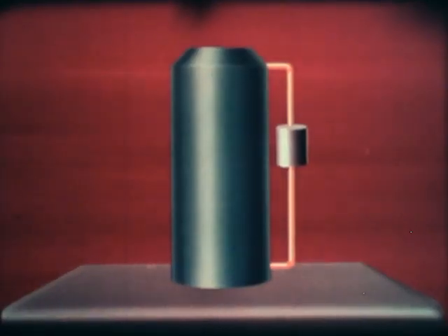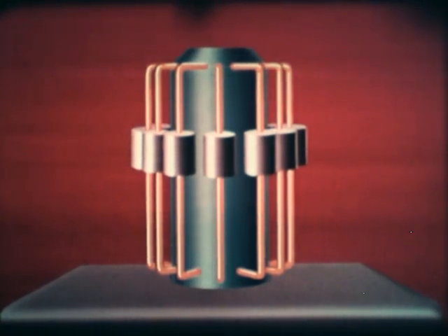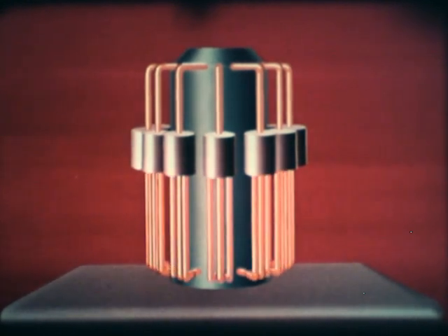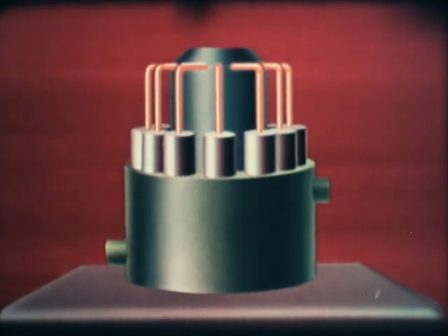High speed will lead to high power. Therefore, the engine as a whole has been designed to operate under these conditions. In particular, an improved heat transfer system was developed. This has been achieved by placing more heat exchange units in parallel. Efficient cooling is ensured by subdividing each cooler tube into many smaller ones. All these are embedded in the cooler housing through which water is pumped.